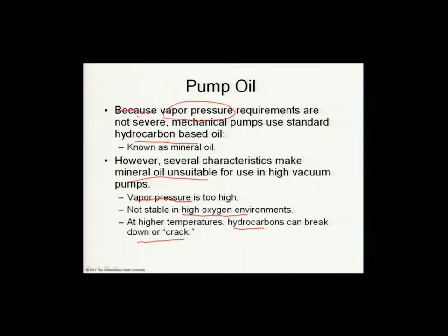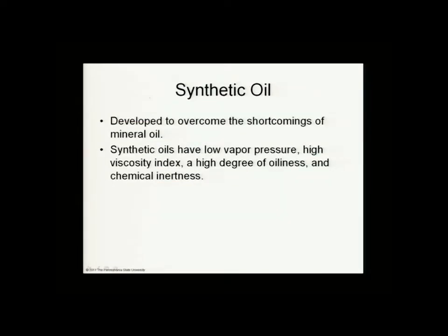If vapor pressure requirements are not severe, mechanical pumps can use them. But if the vapor pressure becomes an issue, then you have to think about moving to synthetic oils. And these have been developed to overcome the shortcomings of the hydrocarbon oils. Synthetic oils have low vapor pressure. These have been engineered to have low vapor pressure, high viscosity, and a high degree of oiliness, so they're really good lubricants, and chemical inertness. So you can use them to a certain degree in situations where you're pumping gases that may be reactive.